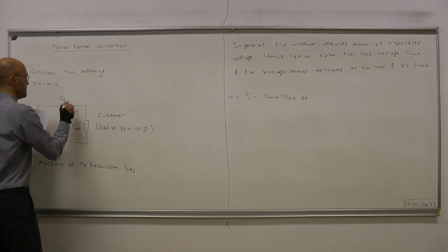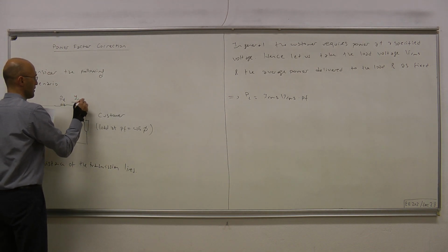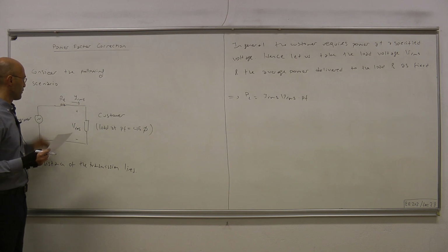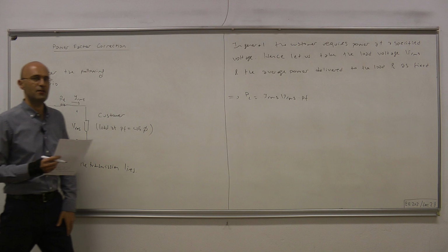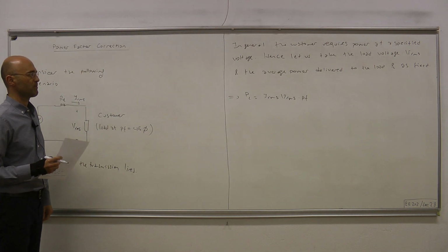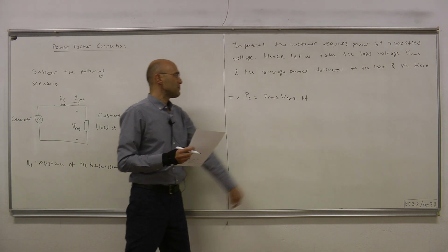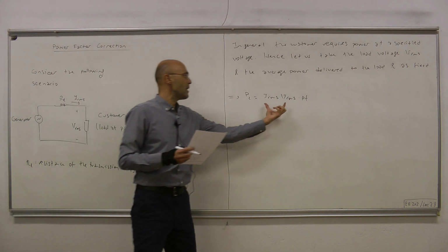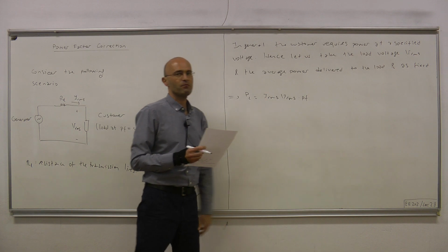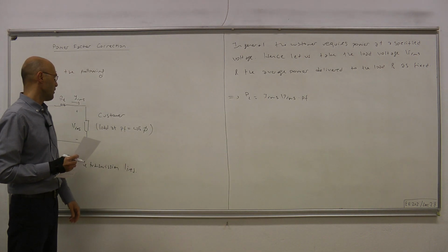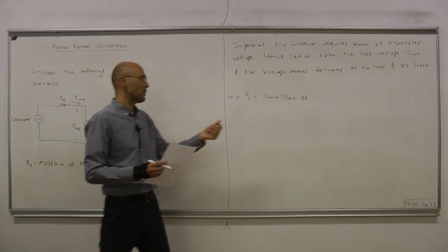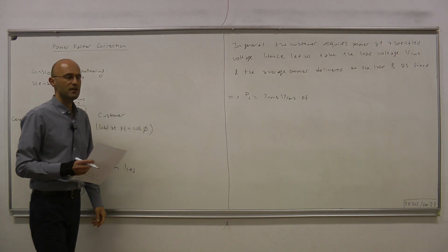This is the RMS value of the current flowing through the transmission lines and then entering the load. IRMS times VRMS, where VRMS is the voltage at the customer side, is the apparent power, and times cosine phi, or the power factor, it is the real part of the complex power, which is the average power delivered to the load.